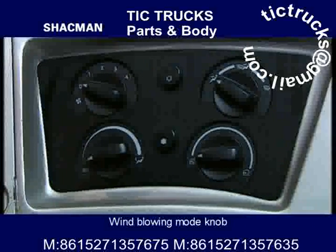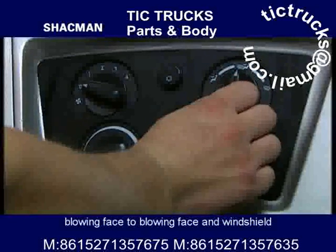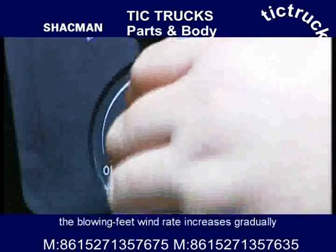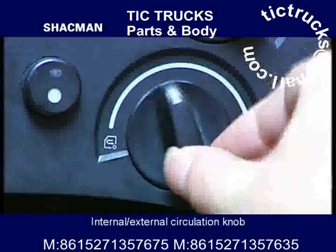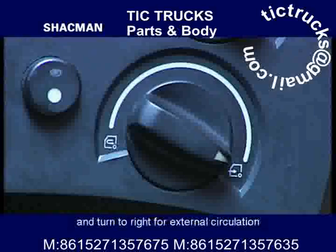Wind blowing mode knob. Wind blowing modes change in order: blowing face, blowing face and windshield, blowing windshield, blowing feet mode. Turn this knob clockwise. The blowing feet wind rate increases gradually. Internal or external circulation knob. Turn this knob to the left for internal circulation and to the right for external circulation.